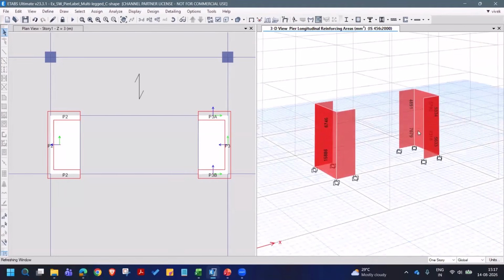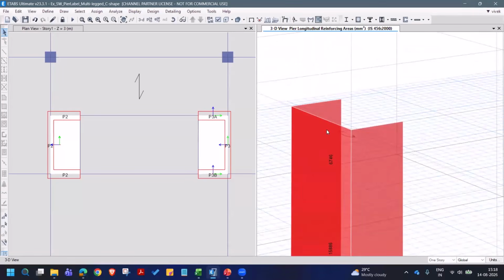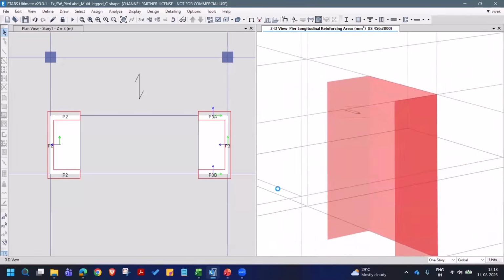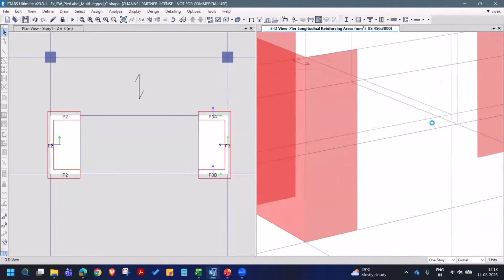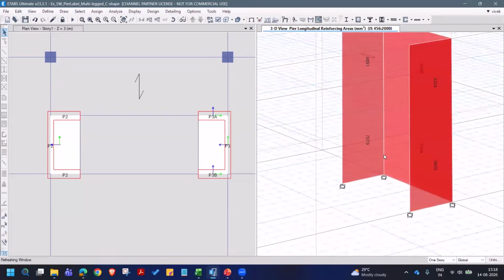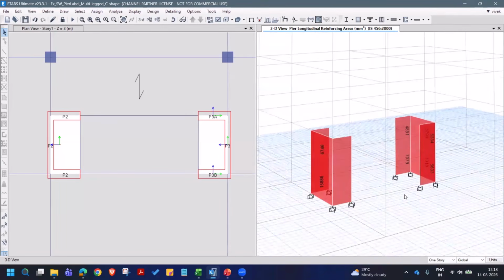If you use a uniform reinforcement, what we generally do, then the top flange is having this ratio of share here, but the actual requirement will be much higher than this 2 meter wall to this 1 meter flange. Right? Both are almost the same. So with the same reinforcement you can miss such things. So the recommendation here is you design for both.